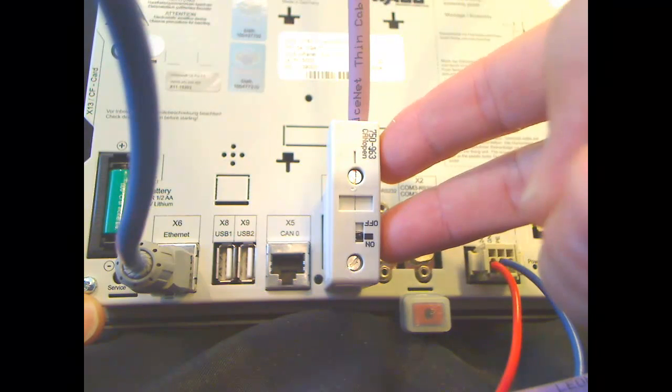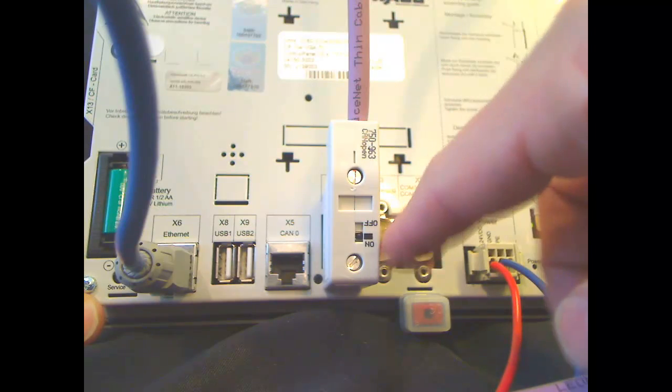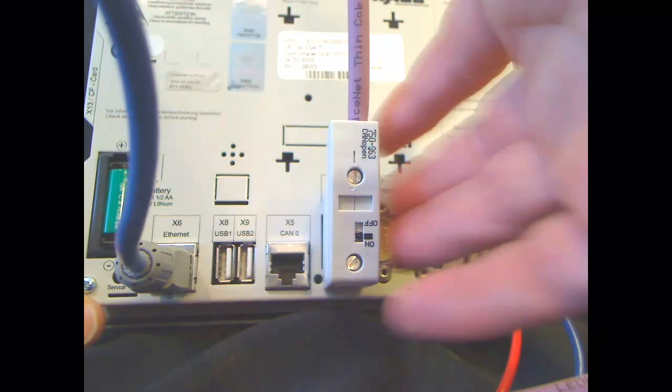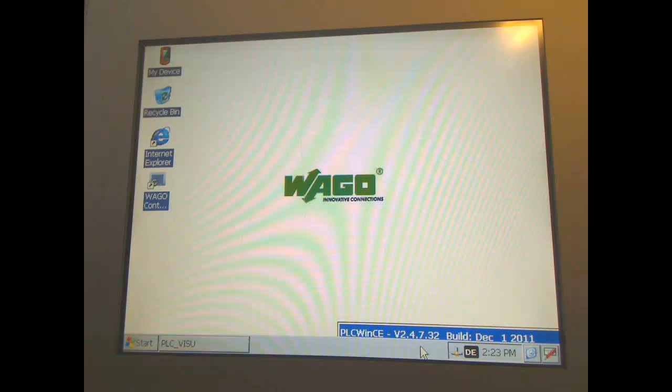This is also a CANopen connector from WAGO with a terminating resistor built right into it. You can see the on-off here. So again, just the different things that you can utilize with this system as far as the various ports. But again, we're going to look primarily at the CANopen, how to set that up. Basically, from the standpoint of the hardware side, it's just a matter of plugging in the cable in this case, and then we'll talk about setup from the panel itself and within CODESYS.